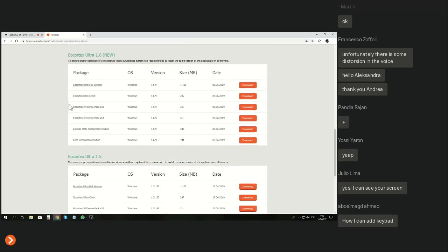Let's say that we already downloaded the files and you now need to activate the license. If you don't have a USB key, you will need to ask your manager to provide you with the license soft key. In this case, once you've got the key, we can launch the installation. You need to choose what you want to install. There are three options: server, client, and standalone. So if you have a monitor, if you want to see, you will need to choose server and client. But if you don't need to see, you will need to choose the standalone.